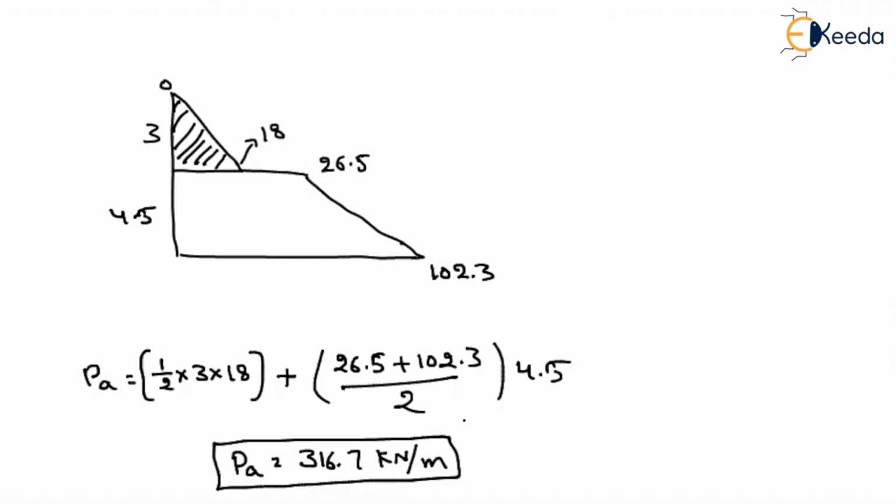Okay, is there any doubt here? Wherever you are having different types of soil, there you have to find out the pressure just above the soil, and also just below the soil, and then draw the pressure diagram in a similar way. Then you will get the correct answers.